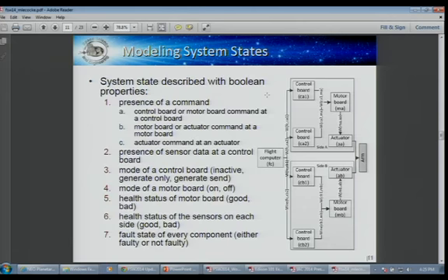It gets more interesting when we start talking about actions. But first we had to define our different states. And for us, for simplicity, for just learning how to do this FDIR process, we kept it at a Boolean state. It was healthy or not healthy, received a command, didn't receive a command. With the idea being that you would have something in front of that that would consolidate your health and status information into a thumbs up, thumbs down on a given Boolean state.